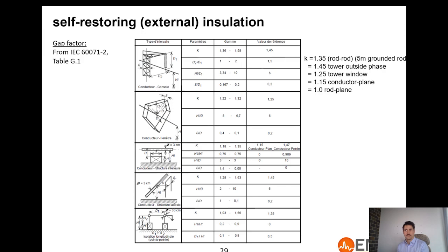The gap factor, this K factor, you have here a little table that explains what to select. So if you have a transmission line, you will take this value. You just have to have that in mind when you do your study. Here again, we are in the case where you have to calculate the BSL and the CFO yourself. Maybe all these things will already be calculated, and you already have the CFO and the BSL, and in this case, you don't need to do all that. But if you have to calculate them, that's the procedure here.